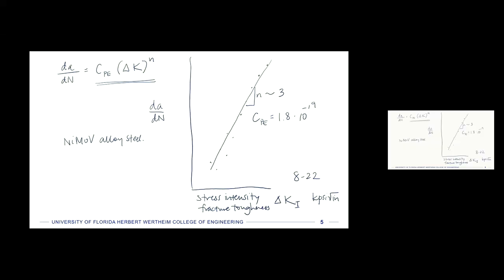And so these units kind of get a little bit crazy here, right? So don't worry too much about the units, but it's just the coefficient so that the line fits along the y-axis there. So this would be for all of those different load levels, okay? So this is Paris law, and you can do the little Paris law like this.